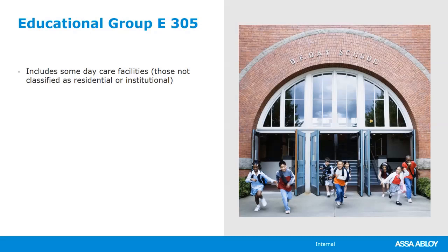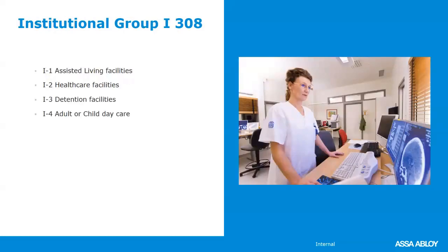You think about our climate nowadays, and if you've got delayed egress on any of your exterior doors that are side doors, and let's say an active shooter is coming down the hallway and people are trying to get out of the building, now you've got a 15-second delay and a trap. So there's a lot of reasons why the higher risk occupancies are not permitted to use delayed egress. And you've really got to look at the why before you determine the appropriate hardware for a building or space.